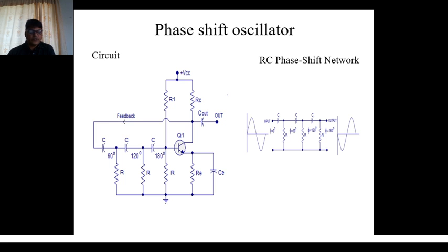The circuit is set into oscillation by a variation caused in the base current, which is amplified in the collector circuit, and it is then again fed back to the RC section. Here again you have to feed back. This is the feedback. The circuit will stop oscillating if the phase differs from 180 degrees.